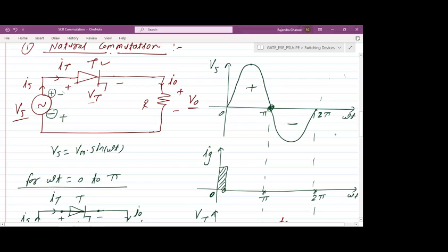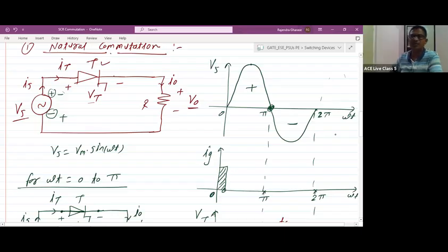We are not using any device. What we are doing is putting a switch there in the gate cathode circuit. And in order to differentiate your gate cathode circuit and the anode cathode circuit, we are using one pulse transformer. That you will understand when we discuss the pulse transformer.